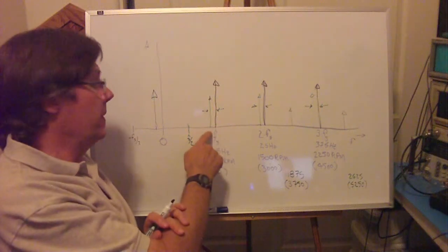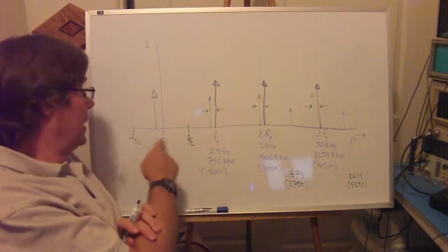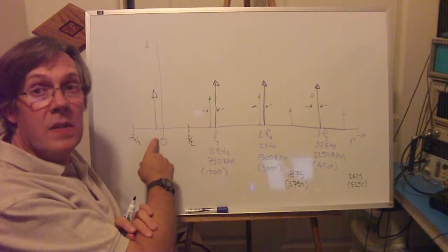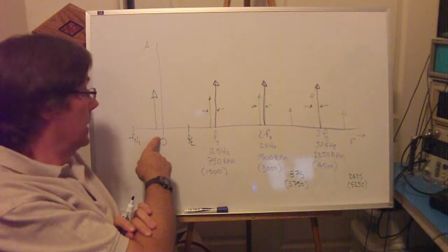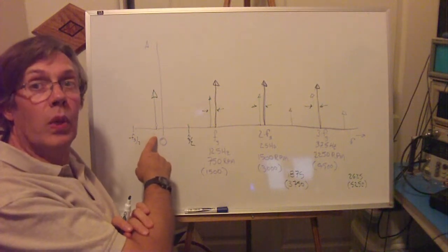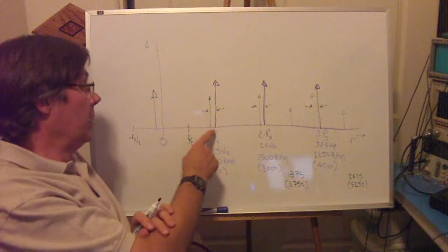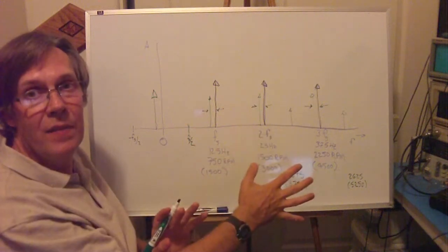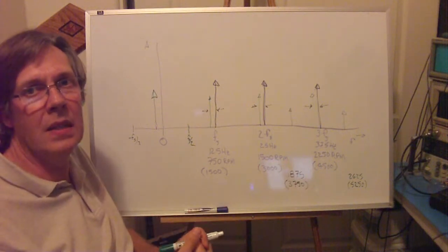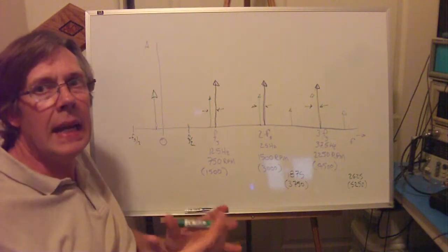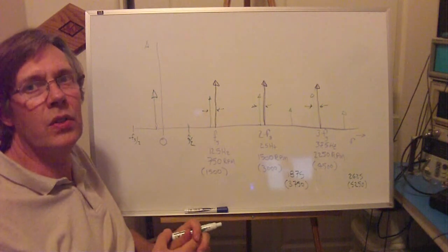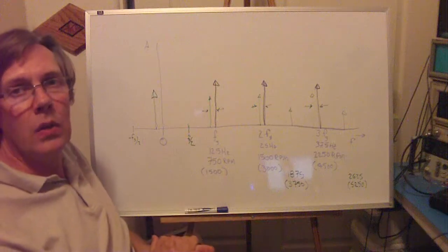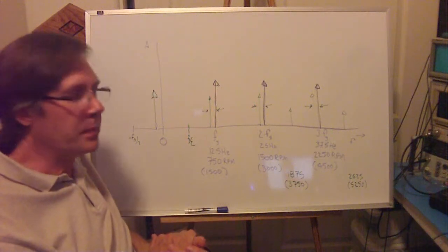In other words, this 50 RPM less than 1500 looks like it's turning at minus 50. So if we really had it rotating at minus 50, that's what it would look like. So it's indistinguishable from really rotating at minus 50 RPM, or 700 RPM, or 1450 RPM. We can't tell the difference. That's why, again, aliasing is a problem: you cannot distinguish what's going on in reality unless you do something to restrict your ambiguity region to only represent what you know you're sampling.